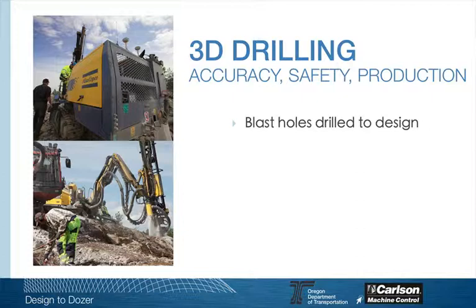For example, if I'm on a construction site with a lot of rock or I'm building a highway, the drill is used to drill blast holes per an engineer's design, so we can blast, move the rock, and come back, blast again, move the rock until we can achieve our design, and then bring in the other machines to be productive. So 3D drilling is a very good candidate for machine control technology, for the blast holes.